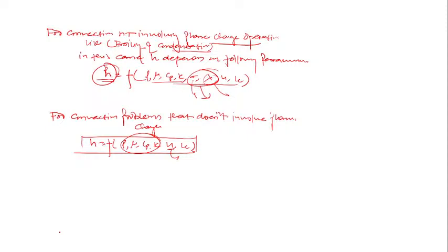So in both cases the rate of heat transfer by convection is different. Both are convection phenomena, but their rate is different. What is the difference in these two cases? Only the value of h has changed. h depends upon the flow conditions. All the properties of the fluid are the same, air is there, but by blowing air through your mouth you are increasing the velocity, and that causes a high value of h.